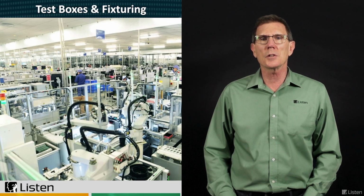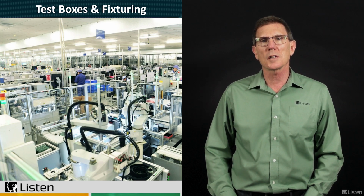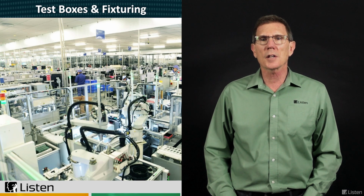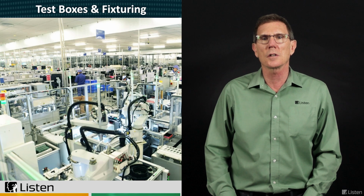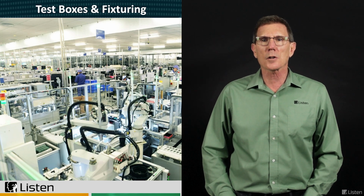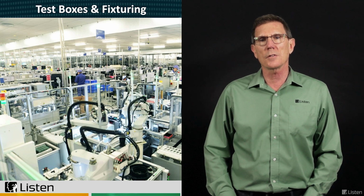errors. Moving beyond the immediate test equipment, the next thing you need to think about is test boxes or chambers and fixturing. I'm not going to spend a lot of time on this as every situation is different. Production lines are inherently noisy places. 80 dB SPL or more is common, especially at low frequencies, and you get a mix of continuous noise like machinery hum or air conditioning, and transient noises like air compressors and stamping machines. These often mask production line defects.